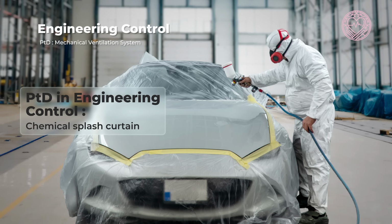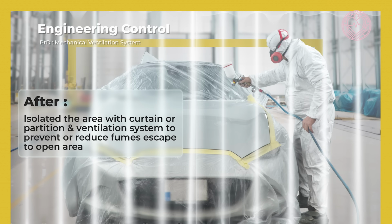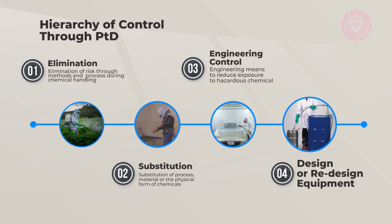PTD in engineering control. Chemical splash curtain. Before, the operator uses solvent chemical to clean parts and the fumes may expose workers in the open area. After, isolate the area with a curtain or partition and ventilation system to prevent or reduce fumes that escape to the open area.